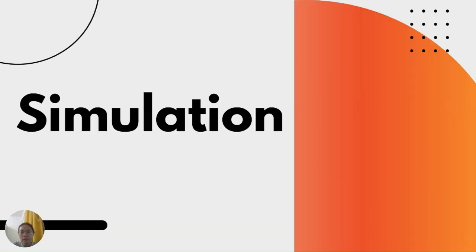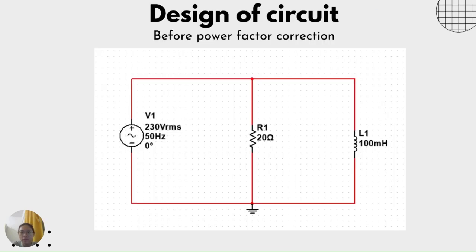Hi, I'm Winchai. I would like to present the simulation part. For the design of the circuit before power factor correction, a 20 ohm resistor is connected in parallel with a 100 mH inductor across a 230 volt 50 Hz AC supply.